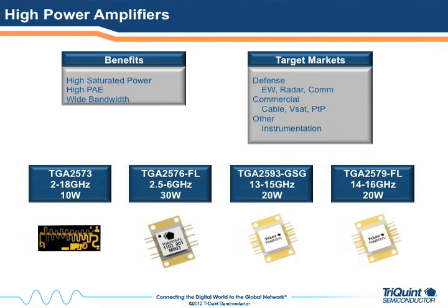High power amplifiers, this is where a lot of the focus has been on product development over the past couple of years, both broadband and wideband. This 2 to 18 part is world class. There's no competition to this product over that broadband that you see there. That was developed through our DARPA program because we were developing the wideband, high frequency quarter micron technology. Again, world class performance at 10 watts over that band. It also achieves about 20% efficiency over that band as well.